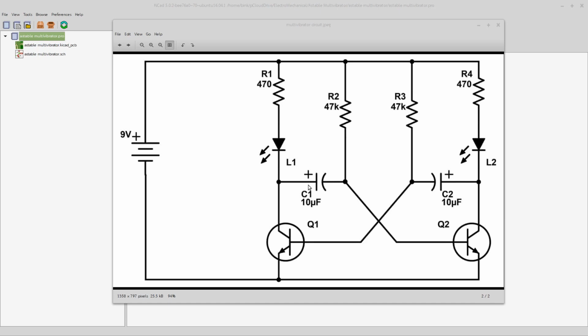And this was actually, I was in a Quora or Ask, somebody asked the question, said basically the same thing, what the hell? And what I found out was that electrolytic capacitors, although we're not supposed to charge them in reverse, can handle up to 1 to 1.5 volts reverse biased. And if this is going to trigger at 0.7, then we end up being fine. And so that's why it works. When I had in my test examples an electrolytic capacitor in there, it functioned and nothing blew up.